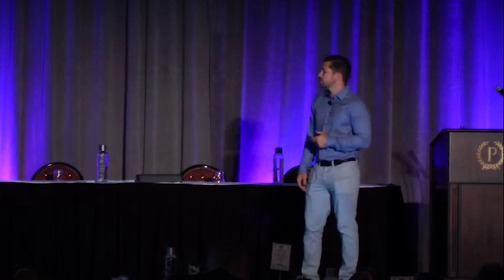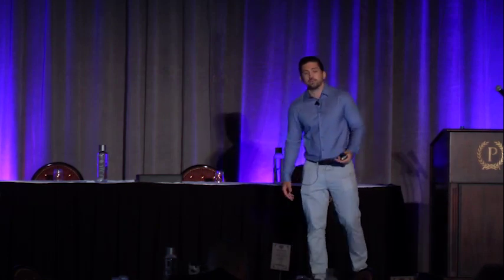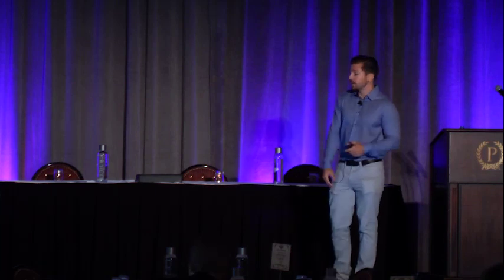So the next common type of structural shoring project that we encounter a lot is equipment and vehicle shoring. There's really two types of this specific structural shoring application. One is when there is a new building going in place. In order to erect it, some heavy pieces of equipment need to drive on existing elevated slabs.